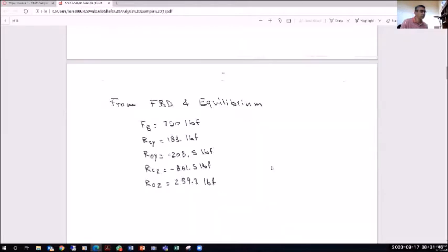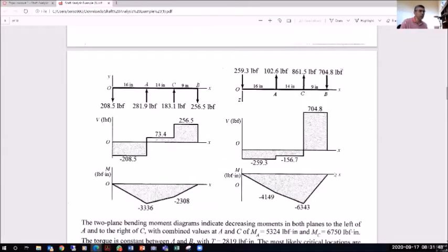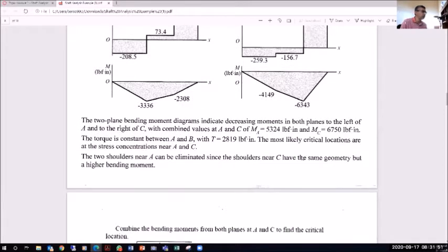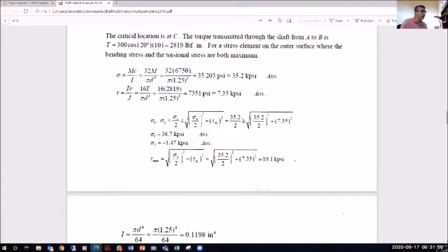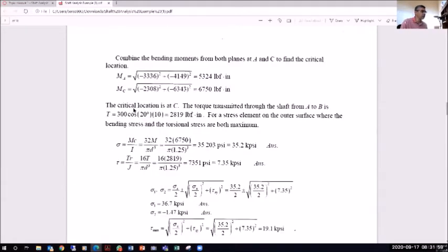FB is 750-pound force, which you had to do the same in homework 1 by finding the tension that was not given in the shaft. After that, you are simply using the solid mechanics equations that were customized for a circular section to find the bending axial stress sigma and the torsional shear stress tau, using the equations. Now, what happens here is we substitute it specifically for a circular section. So we're using the diameter. I find sigma and tau.